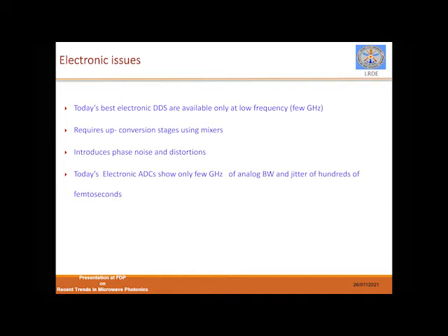And the moment I am using photonic methods for this sampling process, you will agree with me, those who are purely working in the photonics domain, that these components are capable of providing jitter of the order of even a few femtoseconds, whereas conventional electronic solutions may be able to give only a few picoseconds. So when the noise is very low, we will be able to detect the target in a much more precise way, even in the presence of noise.